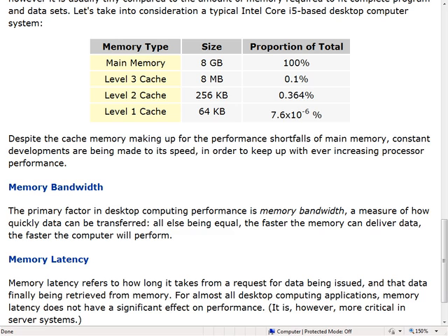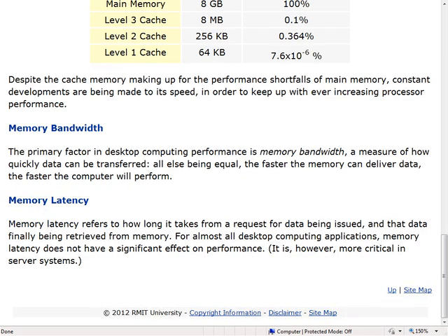I was talking before about bandwidth and latency, and these are the two main benchmarks for memory speeds in a computer, because they're two different things. When the processor requests something of memory, there is how long it takes for the memory to get its act together and actually start spitting out the data the processor is asking for. That's called the latency of the memory, and it's a little more complicated than just waiting a couple of nanoseconds until it's ready. Because of the way the memory is internally organised, memory latency is affected by a few different things, and we're going through that on Thursday.